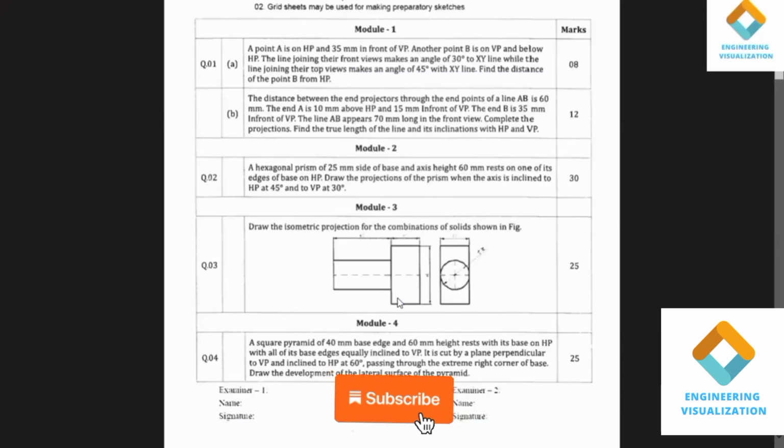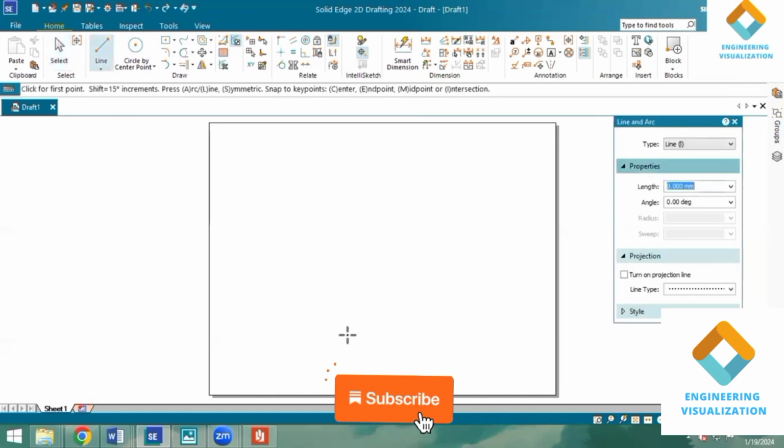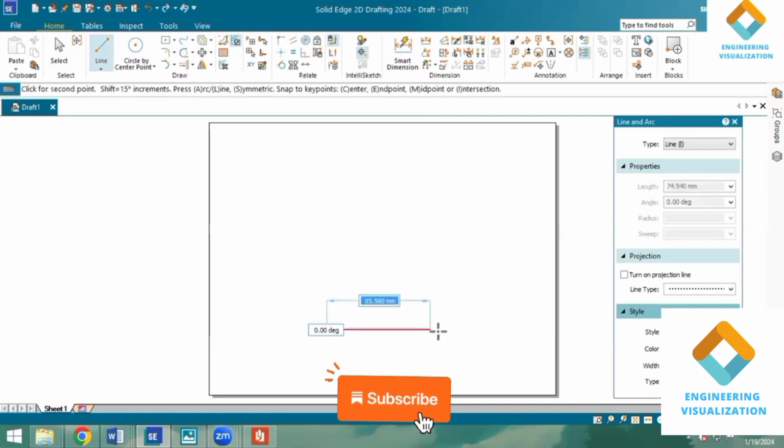Third combination of cylinder and rectangular block. Okay, so to construct here, first we need to take one horizontal line as a reference. From this reference point, I'll draw one line with an angle of 30 degree. So here I'll take 60 mm. Okay, and angle will take 30 degree because in isometric we should use angle 30 degree.